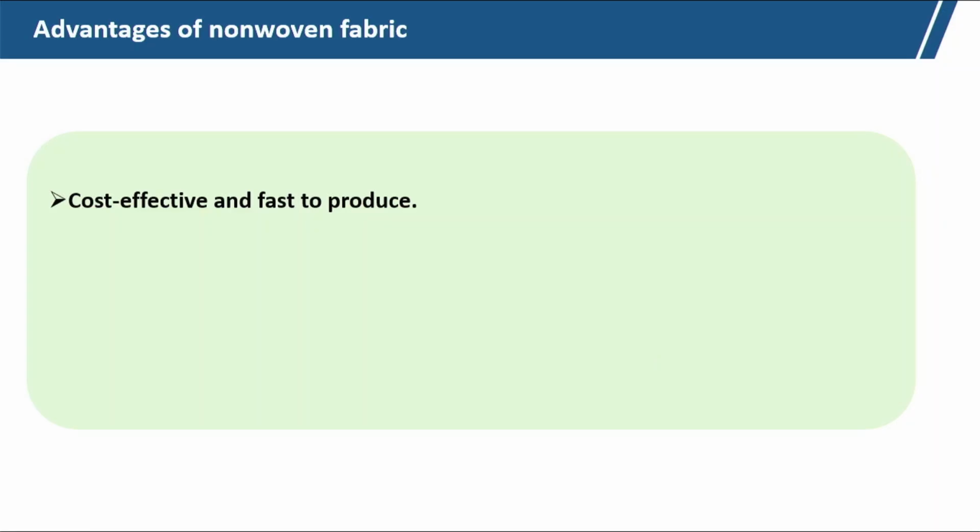So, nonwoven fabric is produced at very high rate, like first web has to be formed, web forming, and its total width is formed at different widths, high width we can form due to the cross laying pattern if we use. So, there is basically no limit of the width, we can produce a very wide width fabric which is suitable for different applications like geotextiles.